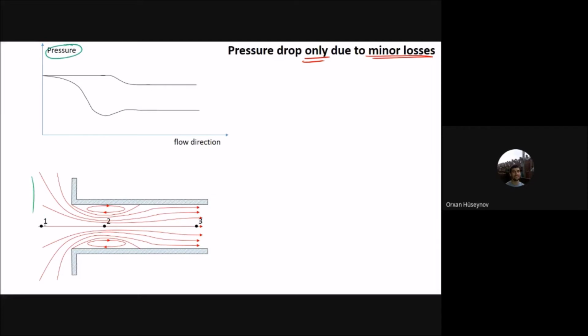So the pressure at point 1, the fluid starts with P1 here. Okay, and then this P1 at point 2, you can see it here. Okay, at point 2 it drops to the minimum value. P2 is minimum. Okay. So why is P2 minimum? Because that area suddenly changes. Okay, this area suddenly changes.